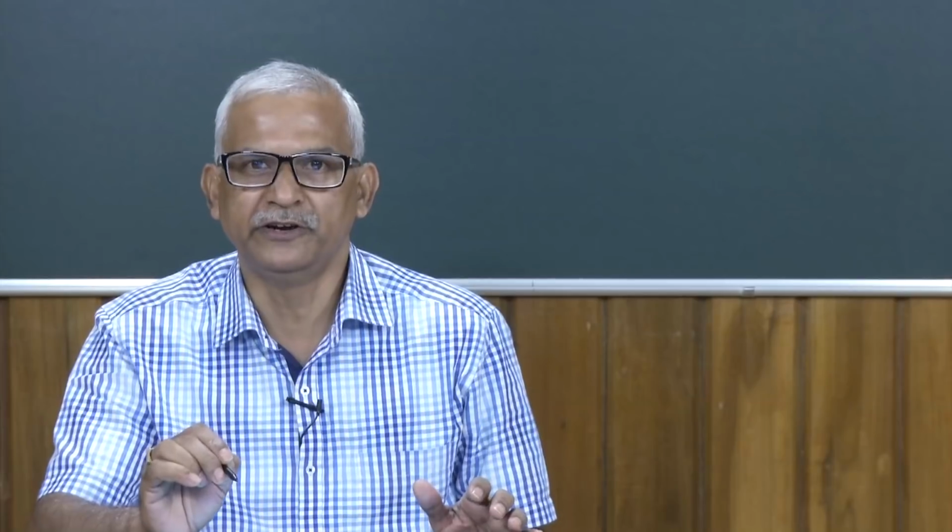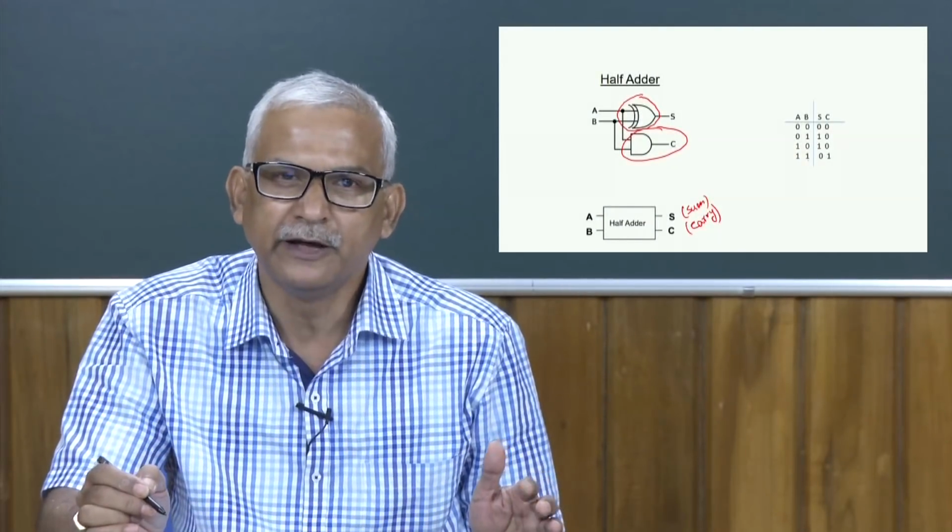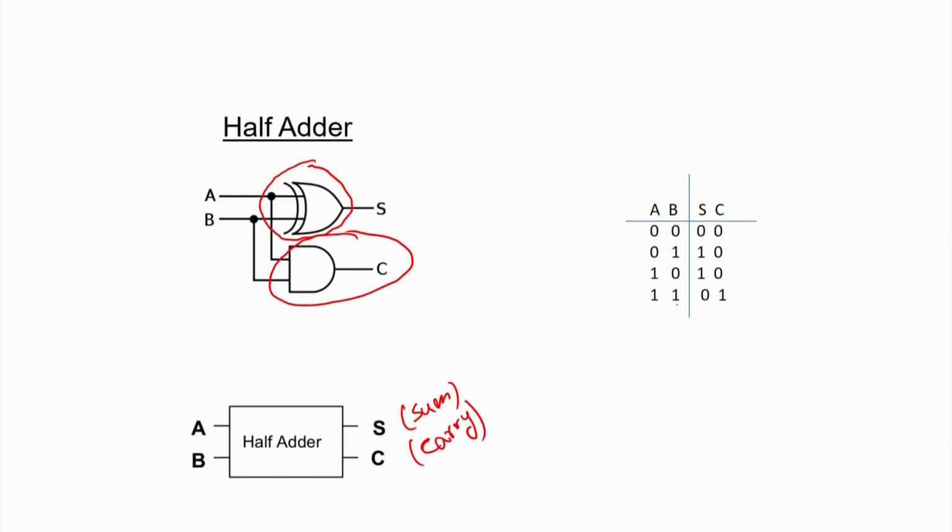When we talk about the half adder, necessarily something will come to your mind, that there may be some other adder also. Just see, this is an adder circuit which can add a single bit number. Now, just consider some 3 bit numbers. Then what will happen? We are going to add it, say 1 and 1 is 0, and it is going to generate a carry 1. Then 1 and 1 we are going to add together, then output is 0, and it is going to generate 1 carry. Now, 1, 0 and 0 is going to give me 1. So, the result is 1 0 0.